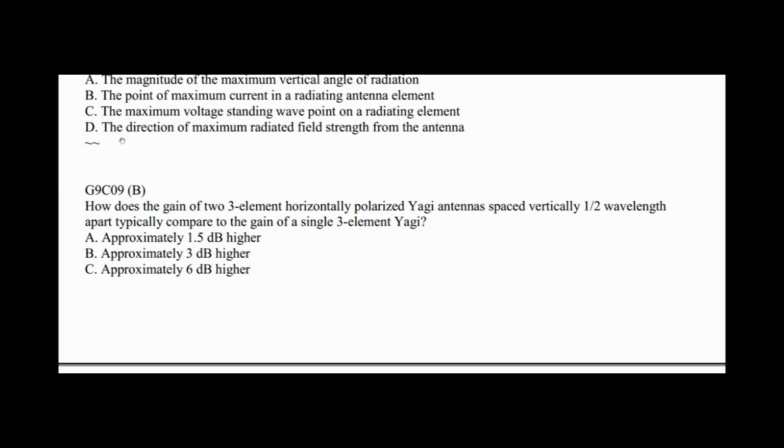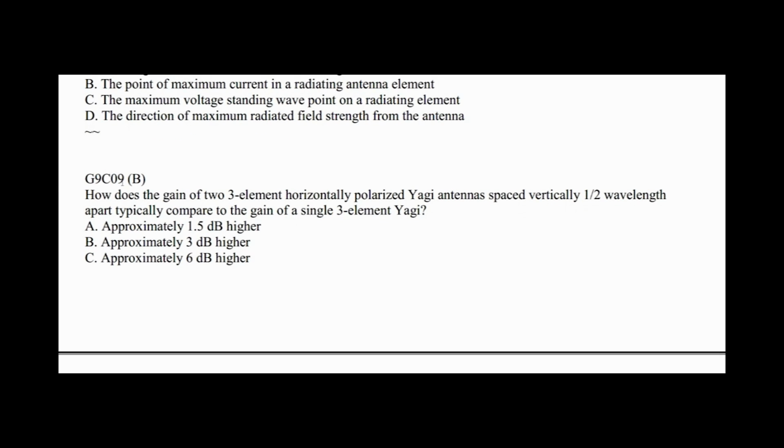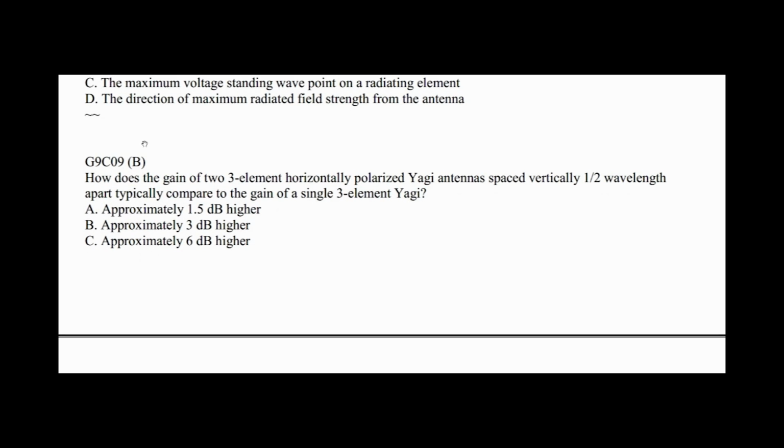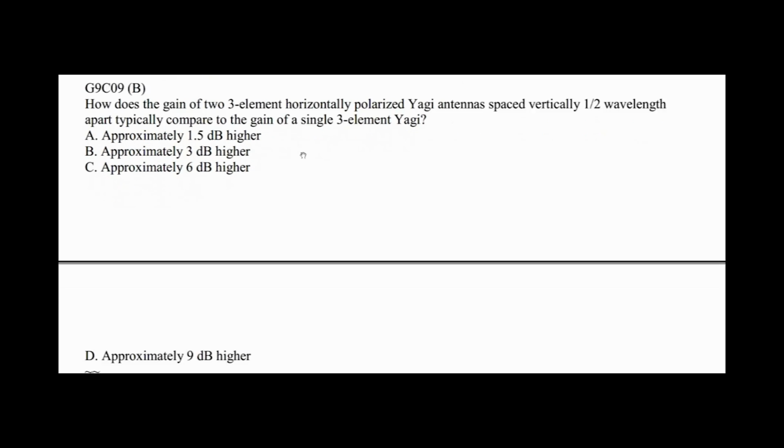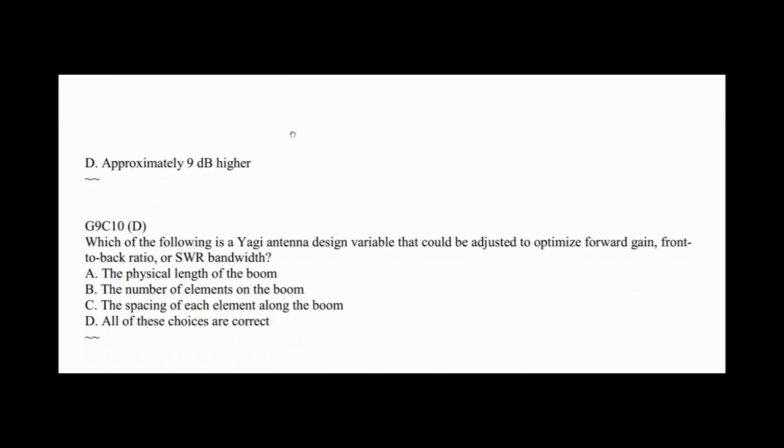Well, I'm doing something like this at home, and there are exceptions to this, but in round numbers, if you double the size of the antenna system, in this case going from 1 Yagi to 2, doubling is approximately 3 dB gain, and that's what they're saying, 3 dB.